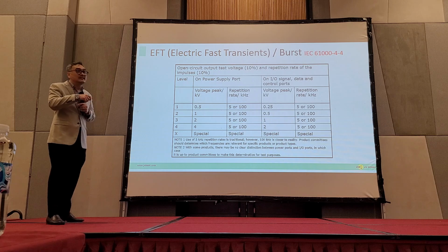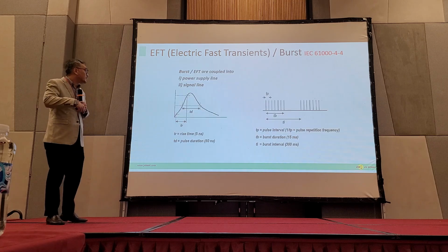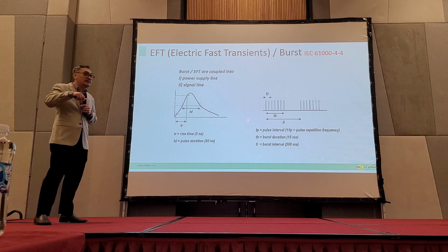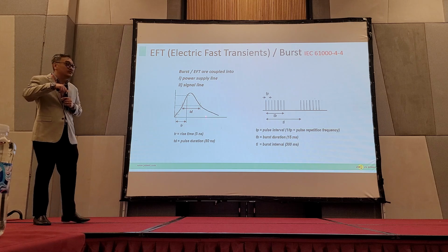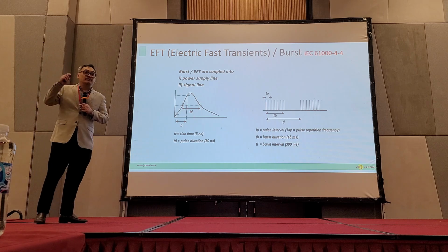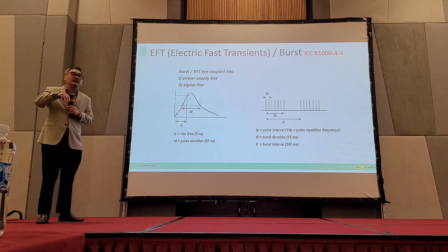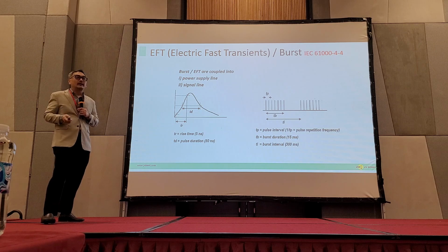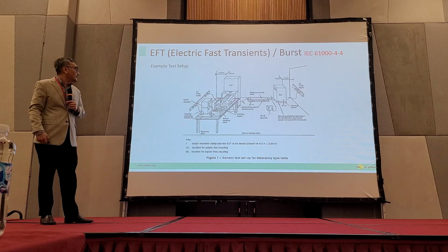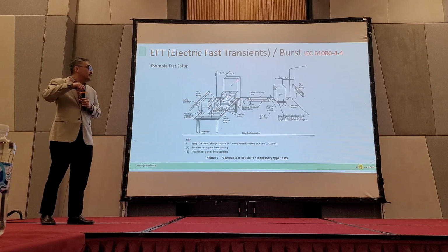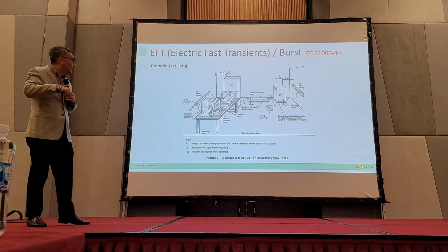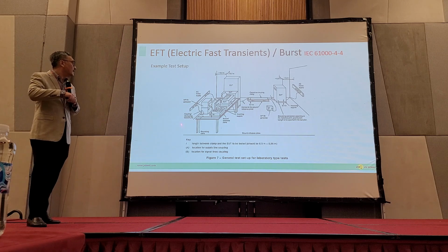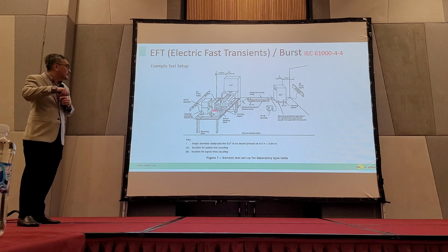But in EFT, if you see, the rise time is very fast and the pulse width is very small. So it's very high voltage, but very low energy. A typical setup that is defined in the standard, you have to follow the same ground plane, then the measurement distance.